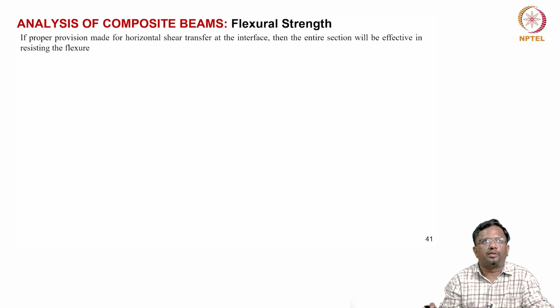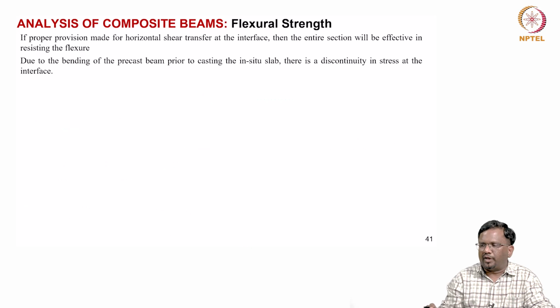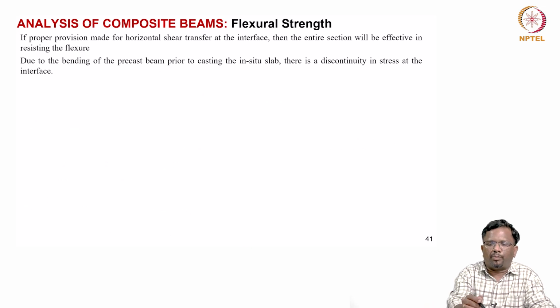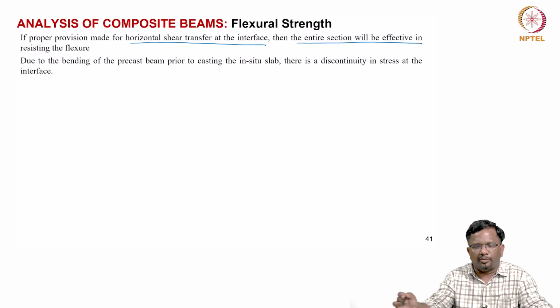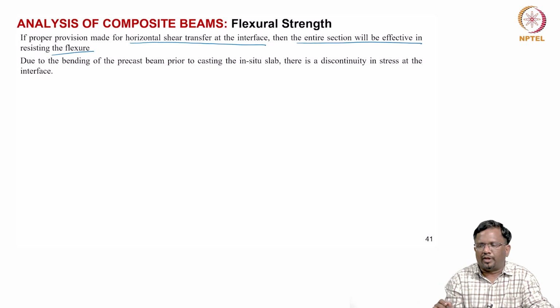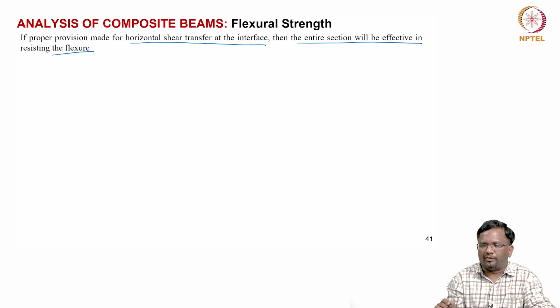So, if you plot it, we have to be careful. If proper provision is made for horizontal shear transfer at the interface, then the entire section will be effective in resisting the flexure, right. So, this is the thing. This is the way that we did.